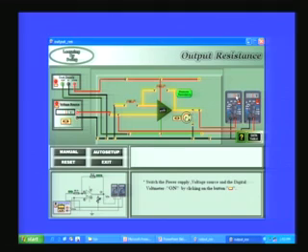The output voltage is half of the previous voltage, and at that time I should know what is the resistance that I have included in the circuit in the variable resistor. For that, I have to disconnect this resistor, and I should make the voltmeter into a resistance meter, ohm meter, and measure at the terminals of these after disconnecting from the circuit. That is what I am going to do by pressing measure resistance.